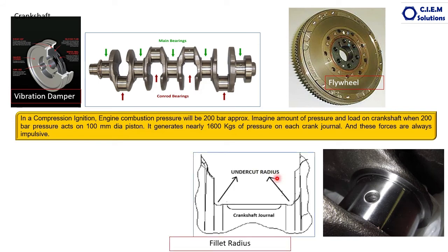This is the crankshaft journal. It's a connecting journal. Okay, main journal. You can see this portion. This portion looks like that. A small dip is there, but with a circular radius you can see. If you expand this, it looks like this. This is the bearing seating area. There is a small undercut, and this is a kind of circular.